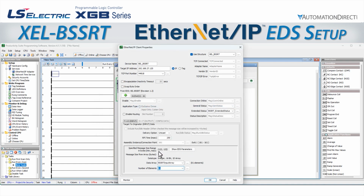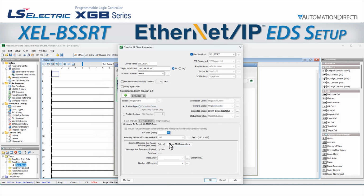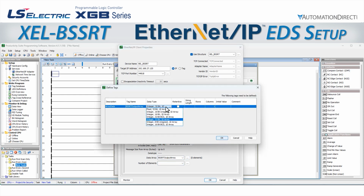Let's run the same setup on our Output tab. We will keep the 250 millisecond RPI and name our array BSSRT Output Array. We will create a 1D array of 16-bit elements and 8 columns to correspond to the 16 bytes of information the EDS requires.